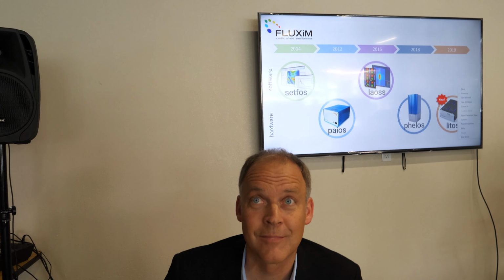And that's going to be on the glass, or is it going to be on the top? How does it work when you put quantum dots with OLEDs? Yeah, there's a plan that quantum dots would be directly deposited on a blue OLED, pixelated, such that each blue OLED gets some quantum dots. The advantage would be to cover OLEDs throughout the whole display as blue OLEDs, and then selectively add green and red quantum dots by inkjet printing, for instance, to achieve the RGB.